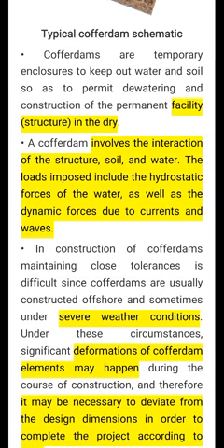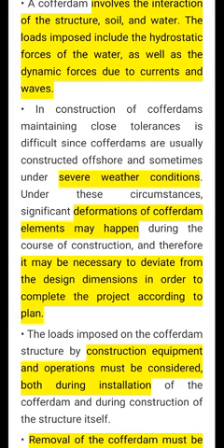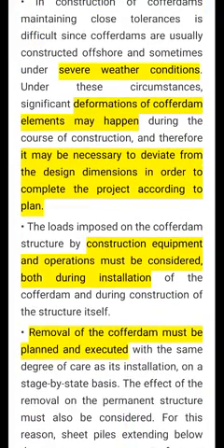Besides that, waves also come there; in marine conditions there will be waves. So to take these pressures or forces from the waves, they have to design accordingly. In severe weather conditions, deformation of cofferdam elements may happen. So the design dimensions have to be worked out to resist those stresses with respect to the project.